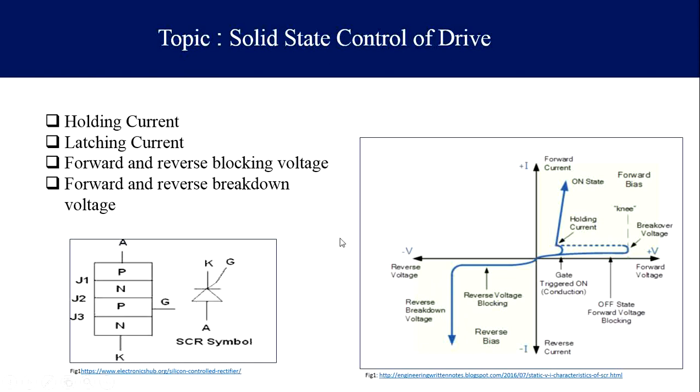Let us discuss conduction mode. Now, how is it going to conduct? See, this was the very high voltage required to make the SCR conduct without gate voltage. Now, what happens if I apply some gate current? So, this is a gate. Okay, so the gate is triggered. There is no need of going in this direction. Directly, very little voltage is required, and the SCR goes into conduction mode when I apply the gate.